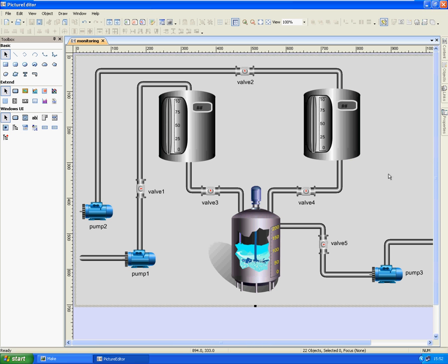In order to make it more pleasing to the eye, we can do further detailed work. For example, take the background wall from the Genius Library, draw the flow with the basic tool of polygon and set its brush property as texture. After finishing the flow picture, we can set the graphic element properties and animation links according to the project needs.